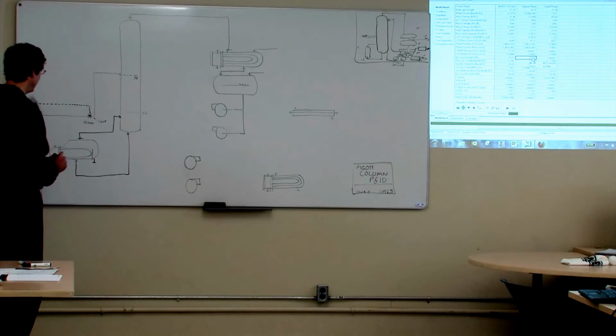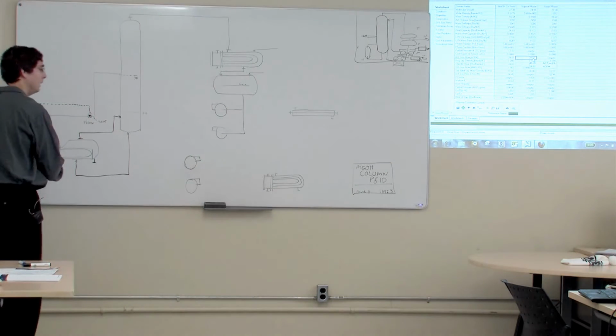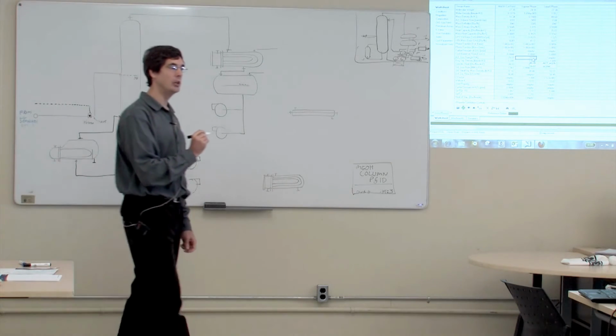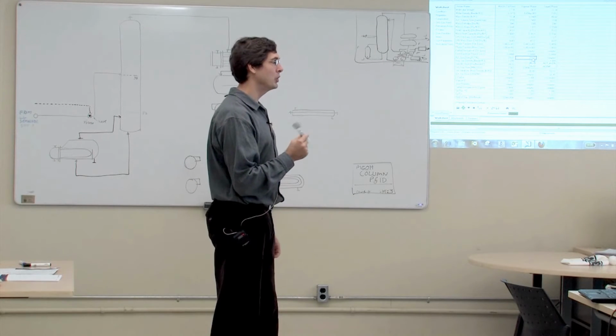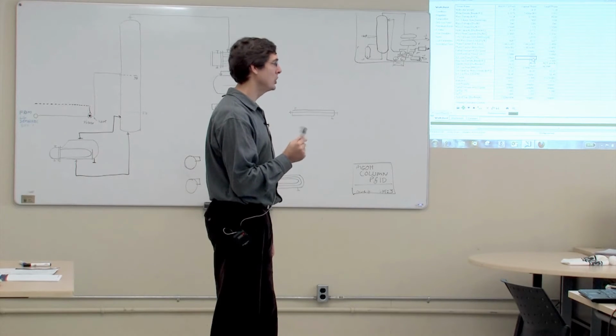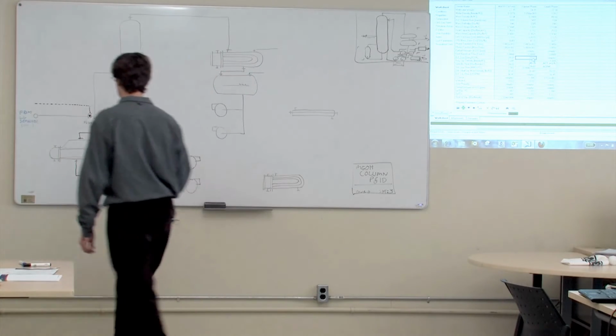Okay, we need to get some steam in there. Steam should be coming into the top of the heat exchanger. Does anybody know what pressure steam we need to use? Simulation rationalization, anybody got the steam? Medium pressure. Medium pressure steam? Okay.